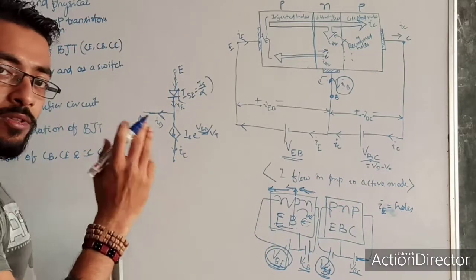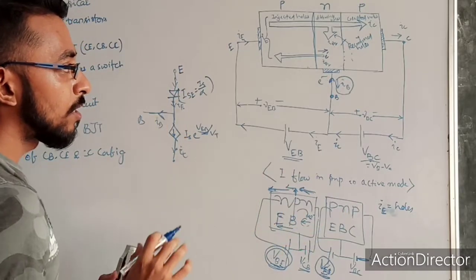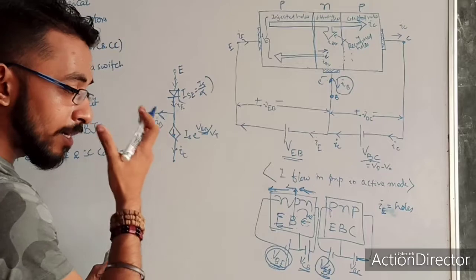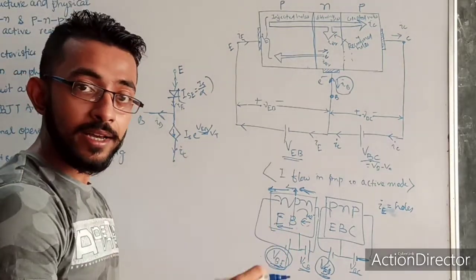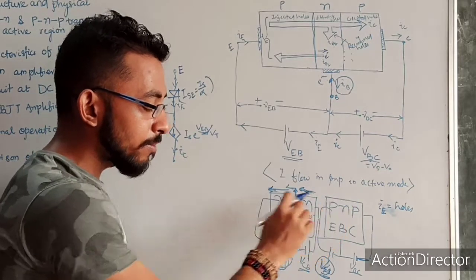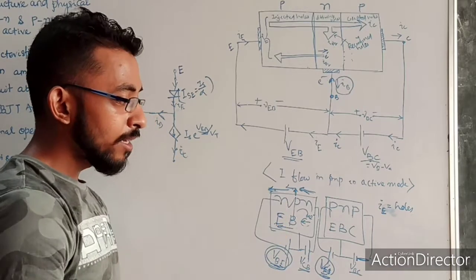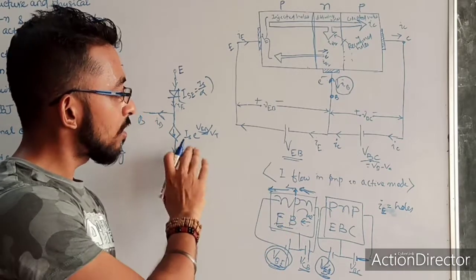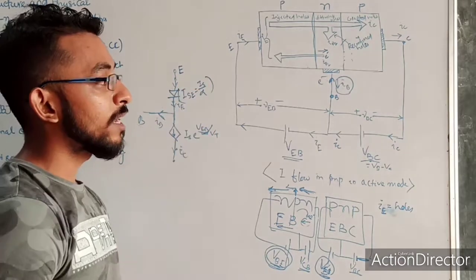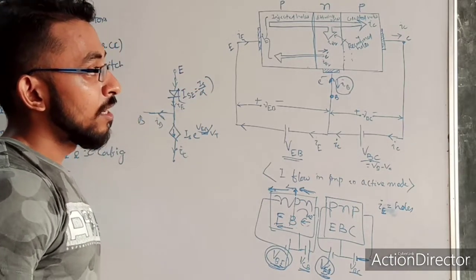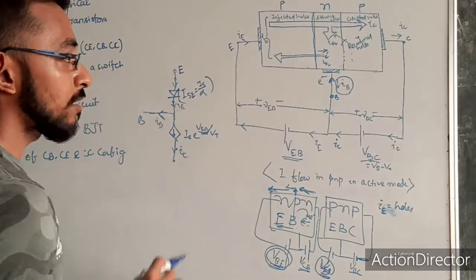Okay, similar to this, there are other three diagrams that you can draw, like NPN, you can draw for PNP. So this is for the PNP type transistor. I am not going to describe all those points again and again. If PNP comes in your question, you have to write all those points that we read in NPN, same as NPN, but you have to change some points like VEB, and the collector and emitter change because of the current direction.